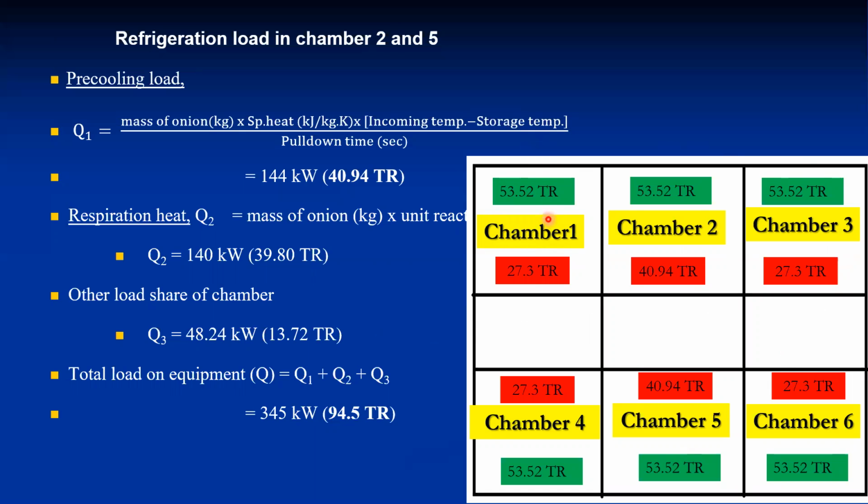two evaporators are required to meet the refrigeration load, instead of one. So to meet this load, that is 50 TR, instead of choosing one evaporator of 50 TR, choose two evaporators of 25, 26 TR each. So here roughly about 27 TR capacity evaporator we need to select, and here around 15 TR each evaporator. So it should be slightly greater than the refrigeration load, by taking some margin.